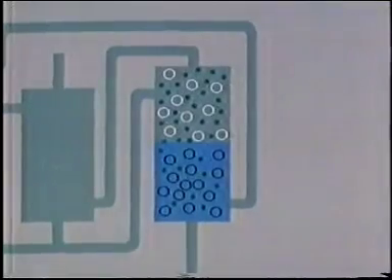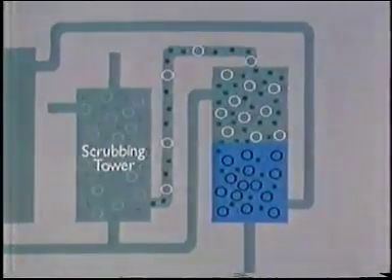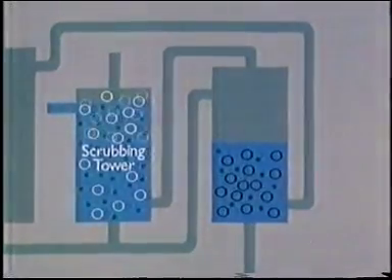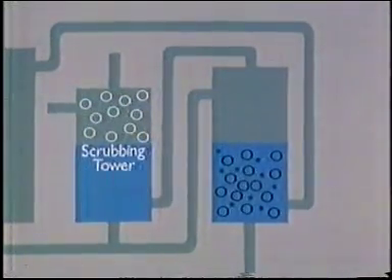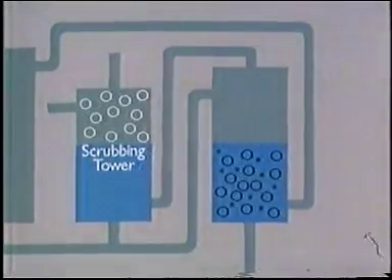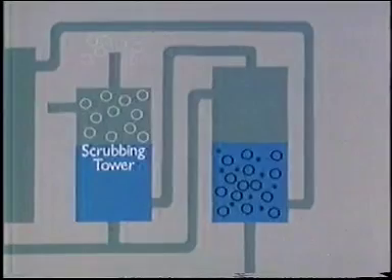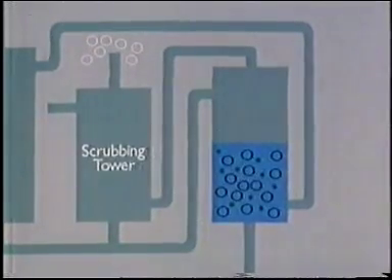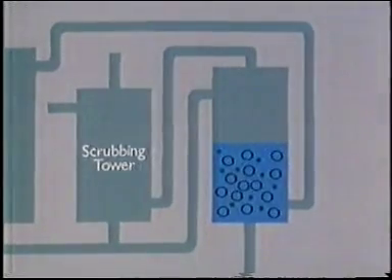The vapors now go on to a second scrubbing tower, where water is used to remove all the remaining ethanol. The other gases that are left go to waste. These are mainly nitrogen and about 15% hydrogen. The hydrogen is formed in the reaction, as you'll see shortly.